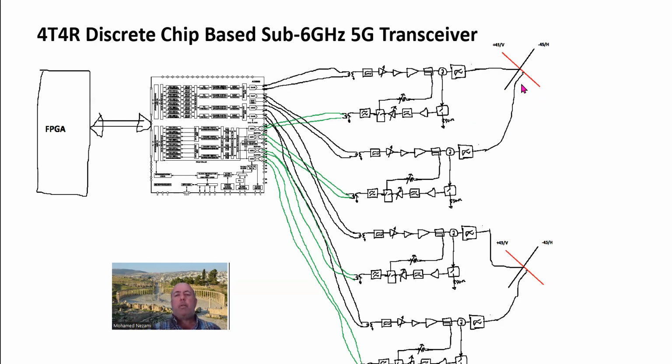You can go in and figure out how you're going to do that. I showed it being implemented for two sets of circular or dual polarization antennas. So you can actually get 4 beams out of this, okay, with 4 different information signals or 4 different frequencies within the bandwidth allowed. You can also split this off and go into other multi-antennas.